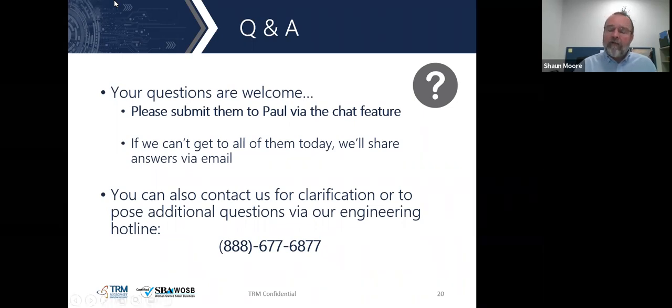For example, I can package ferrite in a surface mount component as well as I can do stripline inside of a surface mount component. So those sorts of technologies can be used either in a surface mount or in a connectorized sort of component. Where you start getting limited as far as going into a surface mount component is thermal management. There we have to be very careful about what we can manage. In addition to bandwidths, when you get into certain packages, they can be limited due to physical size that's available to us.